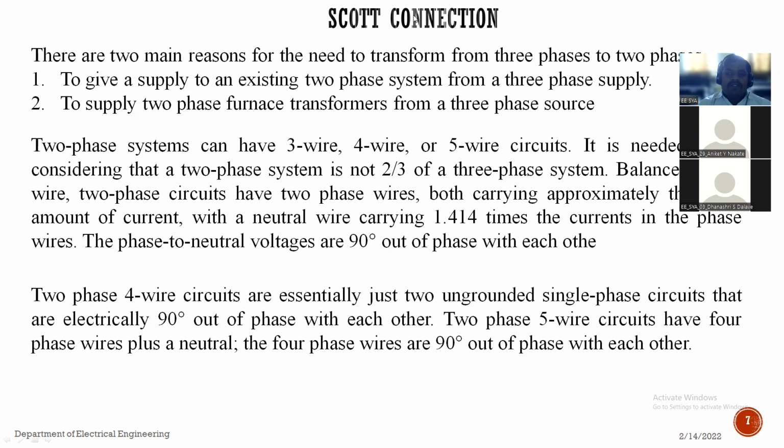Also, the most important advantage is that it will neutralize the effect of the third harmonic, or odd harmonics, which are generated due to the primary winding and secondary winding. The primary and secondary windings generate some odd harmonic content, and this harmonic is reduced, or extinguished, by using a third winding, or tertiary winding, so the three winding transformer is useful.